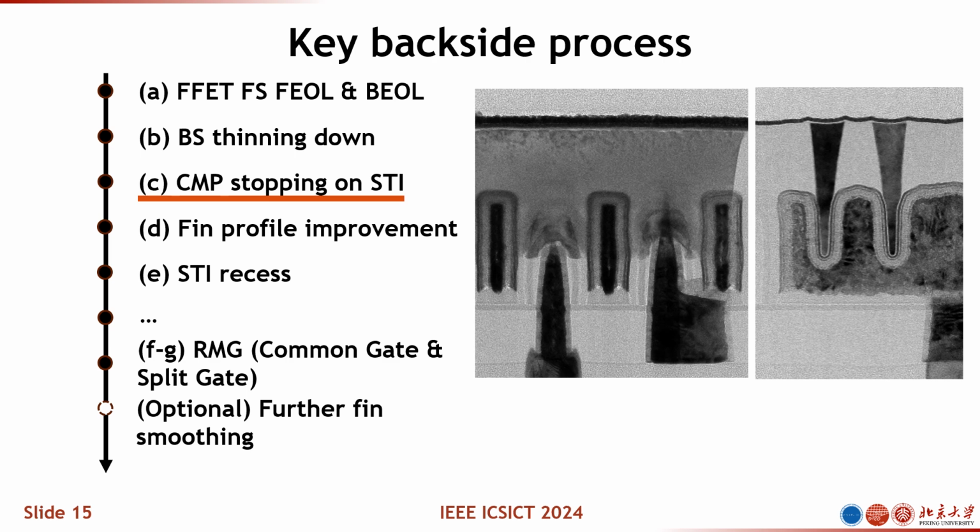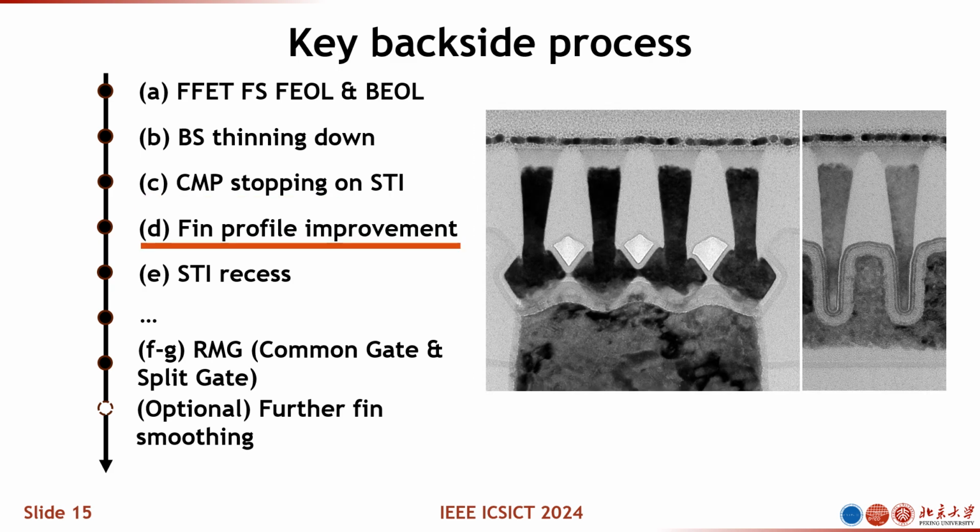And people may also ask a question: your fin looks so ugly because the bottom part of the fin is reverse tapered, right? And this may not be good for the device performance. And I agree with this. So actually you can do some fin profile improvement. As you can see from this TEM image, the fin profile gets a little bit improved.